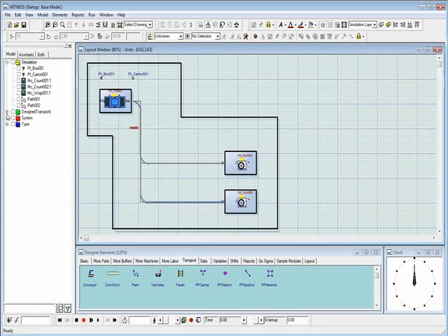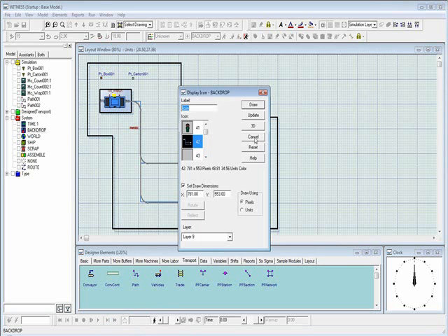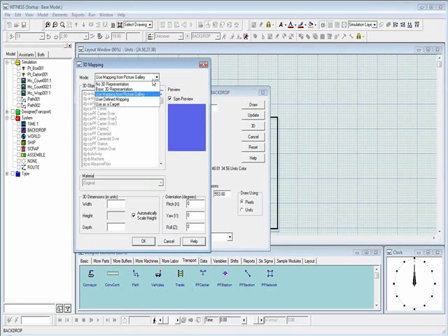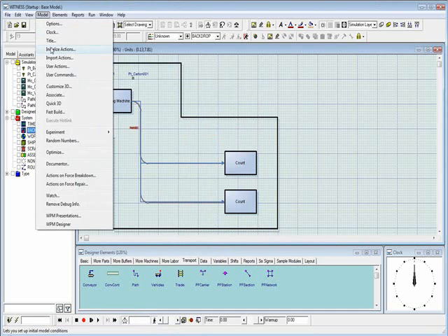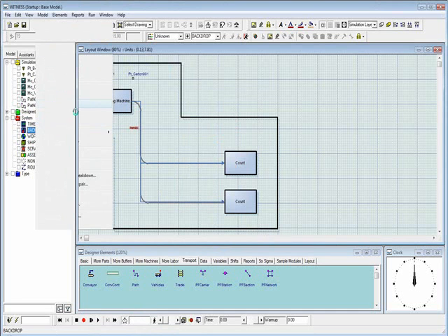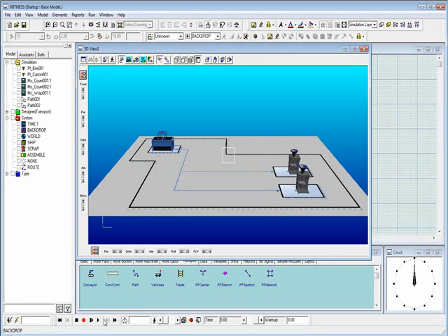We now want to make our background display in 3D better. And what we can do is use this feature called carpets. And basically, our 2D picture, which is our process flow, we can define as what we call a carpet. And that is basically taken into the 3D world and used as a base for our 3D model. So now you can see we've got this. It could be the CAD layout, which would really enhance the 3D visualization of this model.